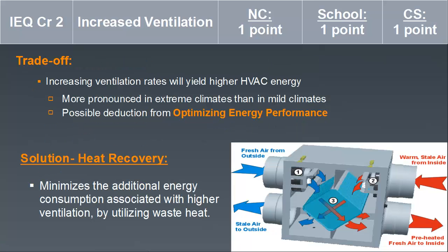Indoor environmental quality, increased ventilation trade-offs could have to do with optimizing energy performance, since higher ventilation could require more energy. Although there are ways to mitigate this, one solution is heat recovery, which minimizes the additional energy consumption associated with higher ventilation by utilizing waste heat.